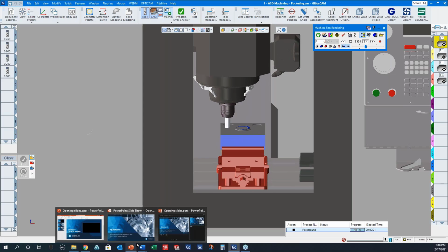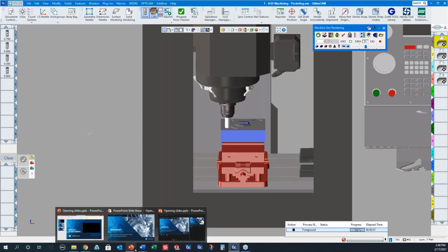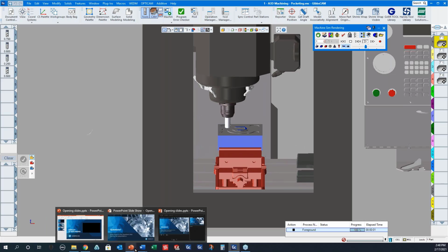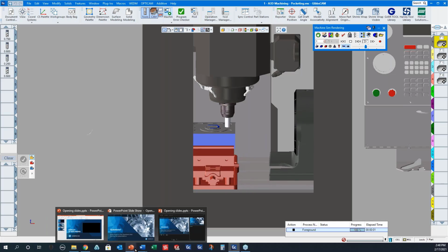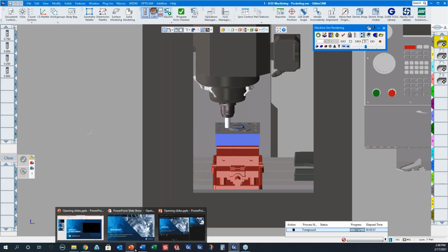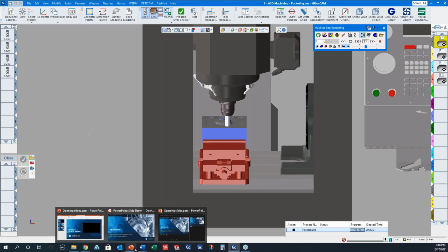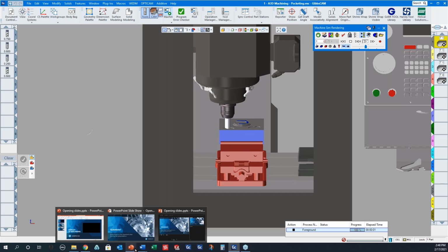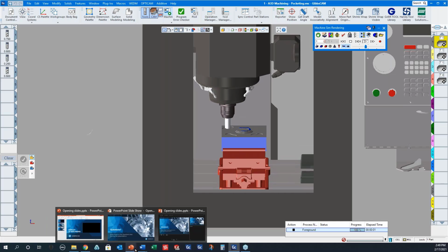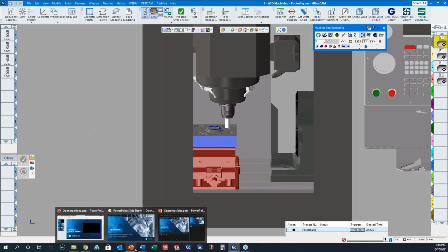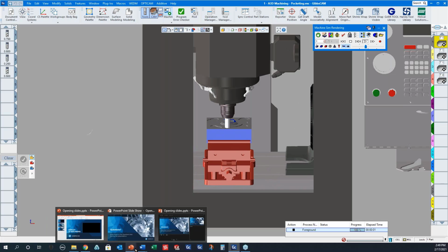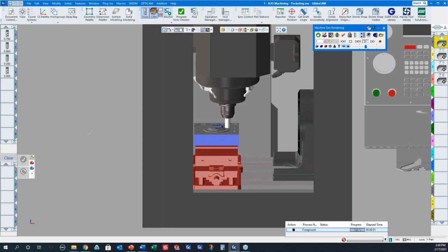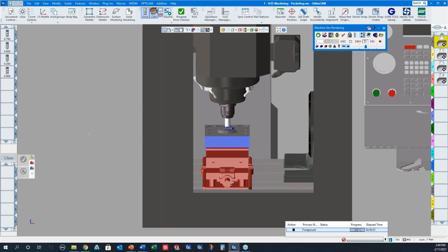Next one. We promote that advanced 3D machining is gouge-free, but are there instances where it will violate the part, or can we force it to violate a part, and when might we want to do that? There's actually two cases that I can think of. One is if you have the surface tolerance too loose.